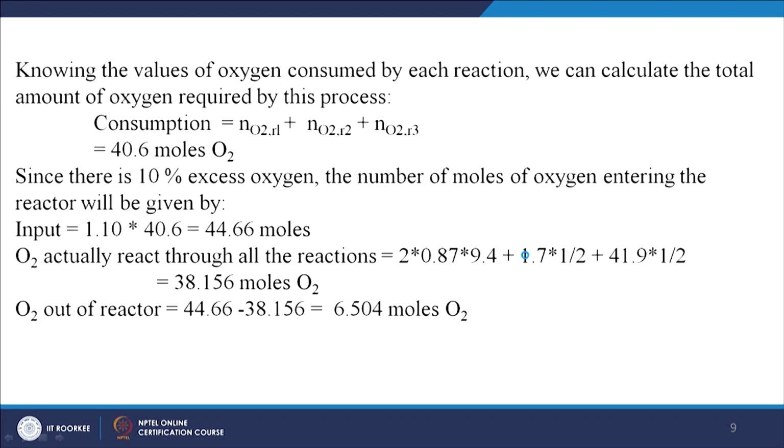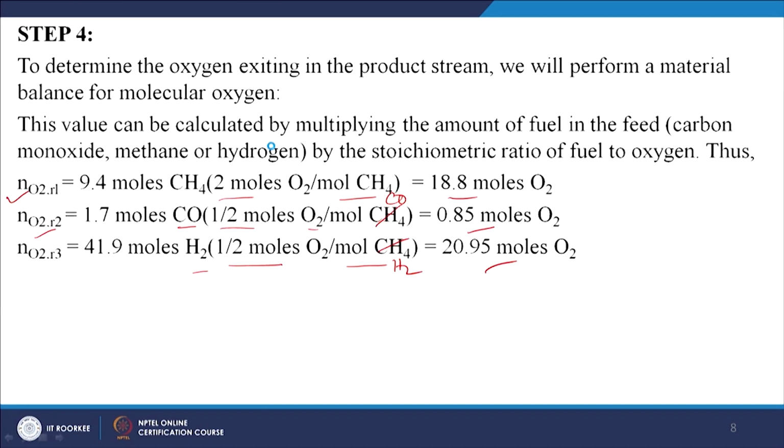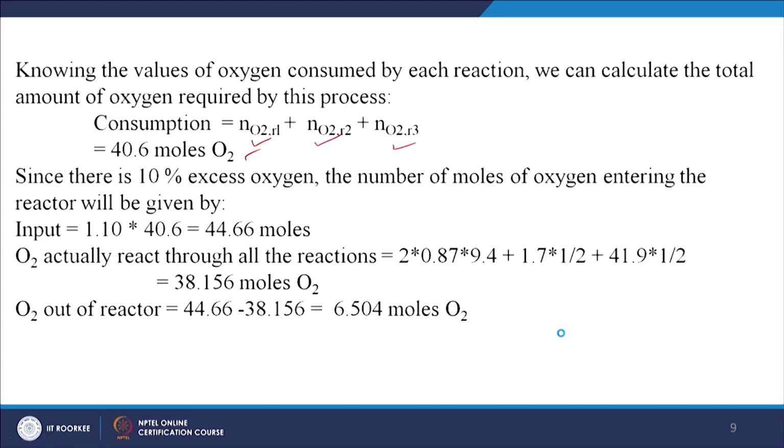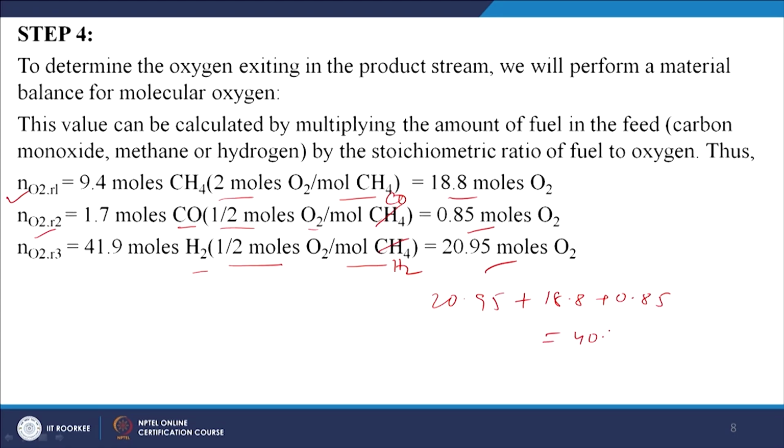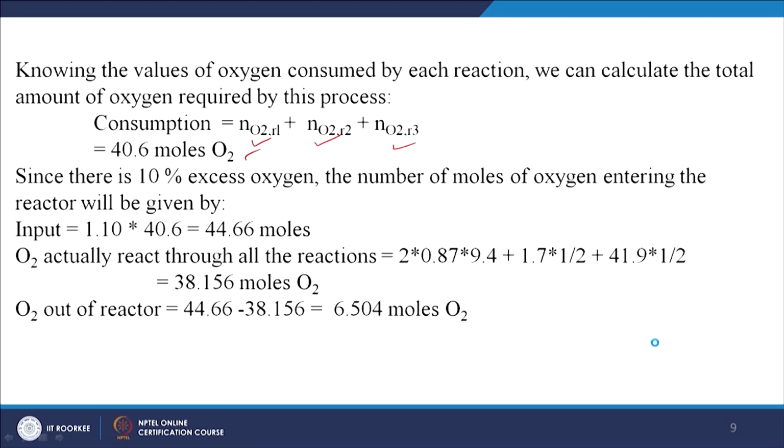The oxygen consumed for the methane reaction, for the CO and for the hydrogen: 20.95 plus 18.8 plus 0.85, that is equal to 40.6 moles.